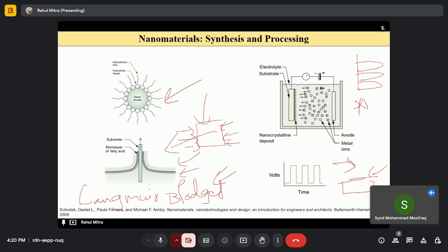So to avoid this columnar formation, what we do is apply a pulse current, where the voltage rises and drops. For example, if you are applying 5 volts, we start at 0 seconds and give 5 volts for 3 seconds, so we have a voltage pulse, and then again we drop it to 0 and give a dwell time of about 10 seconds. So we create a pulse of voltage so that we create nucleation sites, not the growth process.